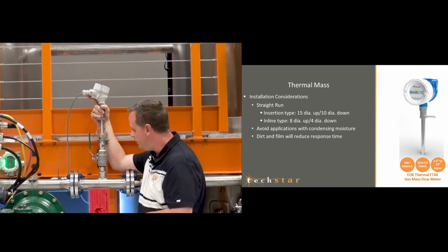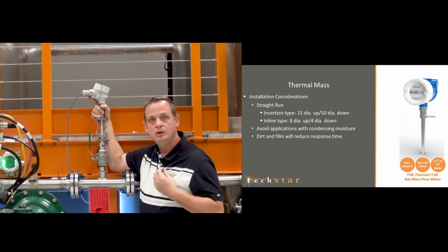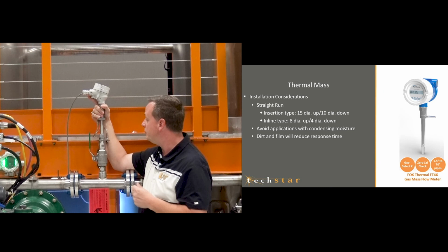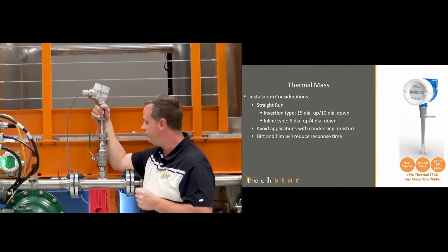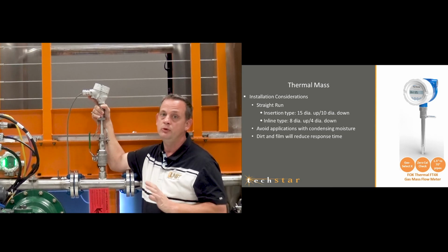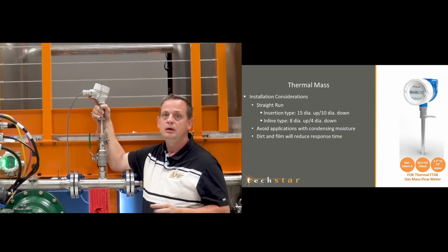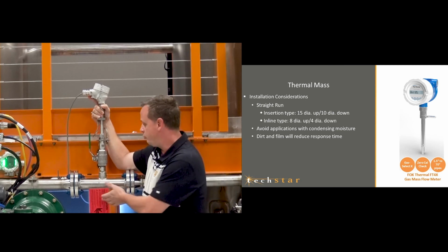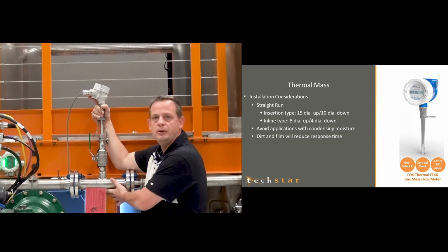These are great flow meters. They work based off of some temperature. I know Shannon was just telling you how they work. They're really good flow meters. We do need to have moisture as a consideration. We don't want excessive moisture in the line. So it needs to be installed in place to kind of mitigate that moisture buildup, where it doesn't kind of build up here on the bottom of the line.